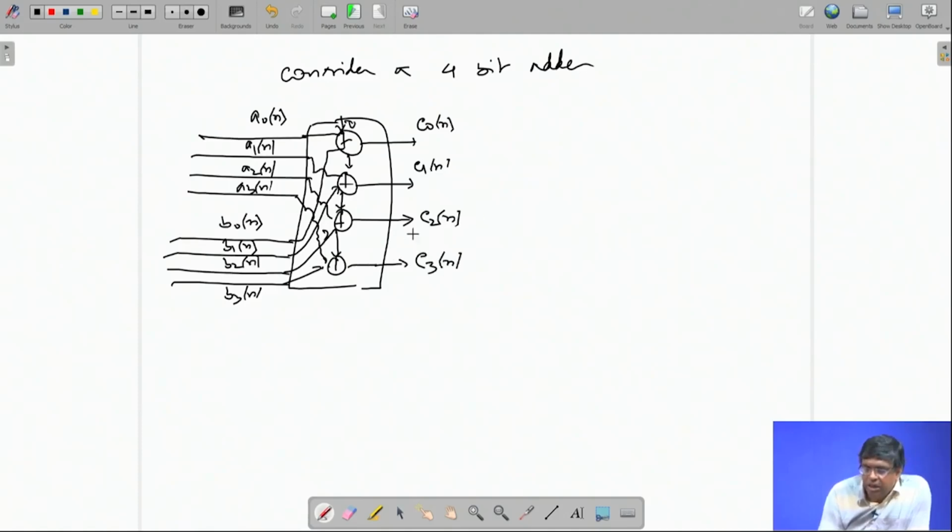So, you see, as I was telling, the processing in this case is an adder between A0, B0, the same processing is done between A1, B1, the same is done between A2, B2 and the same is done between A3, B3. So, 4 adders in parallel. So, I am paying 4 times hardware in terms of adder hardware. Okay. This is an example of fully bit parallel or word serial system.